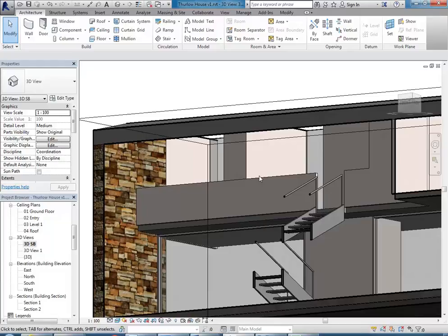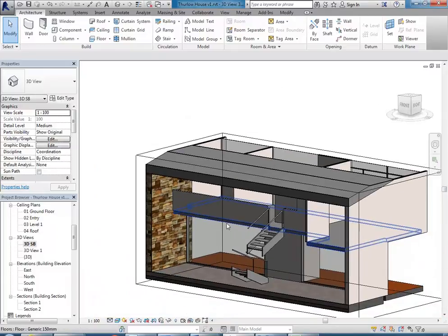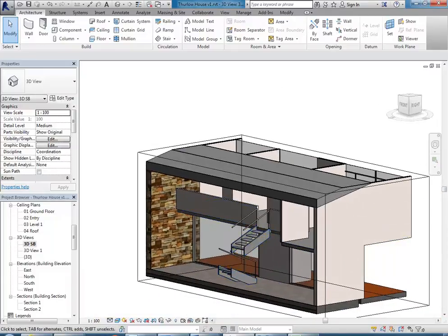So when you make the wall, set the height to unconnected instead of setting it to a level. You can do it before you draw the wall. So where it says height, click on the wall button, and then you've got height above that on the green bar at the top of your screen. And to the left, you've got the level. Leave it on height, and then next to that, you've got the level. So choose there, and you can set it to unconnected, and then type in 1000. Okay, so like I was saying, I'll give you some time to work on the walls, and then we can have a look at door and window types.